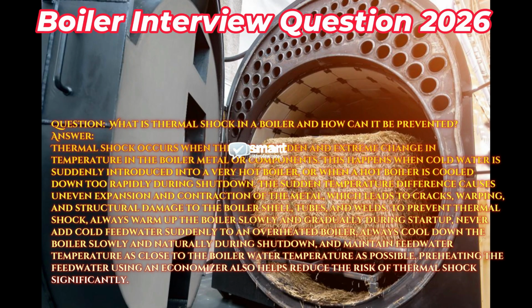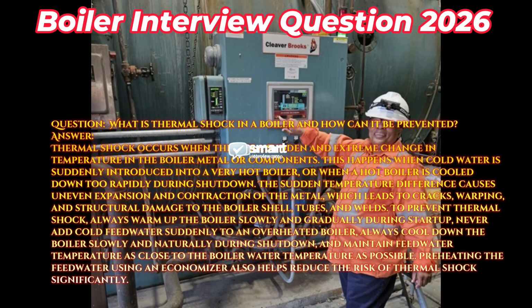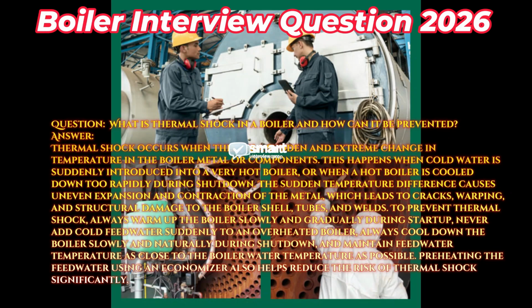Always cool down the boiler slowly and naturally during shutdown, and maintain feedwater temperature as close to the boiler water temperature as possible. Preheating the feedwater using an economizer also helps reduce the risk of thermal shock significantly.